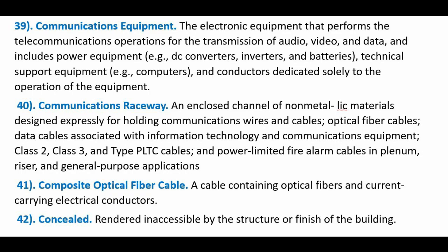40. Communications raceway. An enclosed channel of non-metallic materials designed expressly for holding communications wires and cables, optical fiber cables, data cables associated with information technology and communications equipment, Class 2, Class 3, and Type PLTC cables, and power-limited fire alarm cables in plenum, riser, and general-purpose applications.